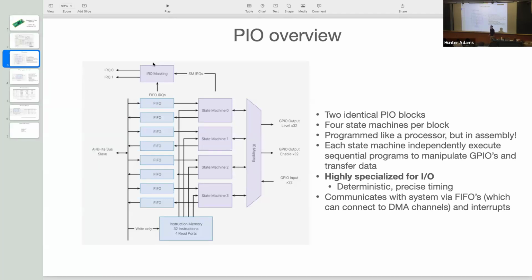The CSDK includes functions that allow for you to do this from your application code if you wanted to. So you could call a function called something like PIO state machine 1 send and put a value there, and your code would then pop whatever value you placed in the argument into this FIFO.